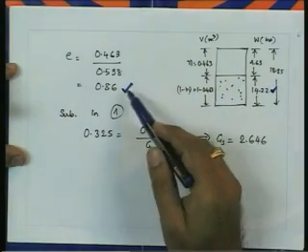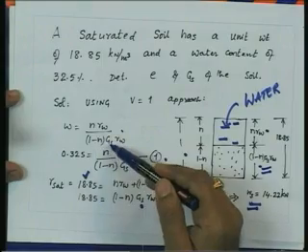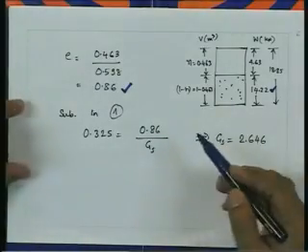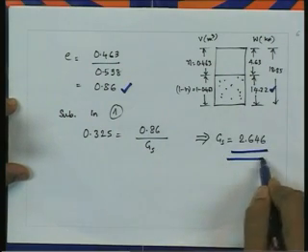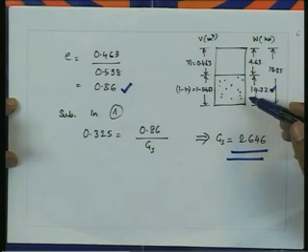Substituting the void ratio in the previous expression 1, that is w is equal to n by (1 minus n) Gs, we will get the specific gravity of the solids as 2.65. So, what we did is use the phase block method, in which we set the total volume as 1, and we used the given values in the problem to deduce the asked parameters like void ratio and specific gravity of the solids.